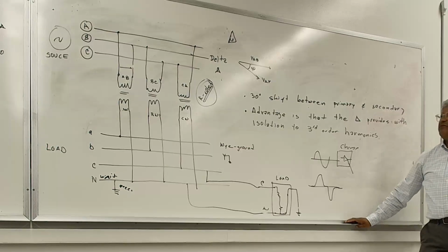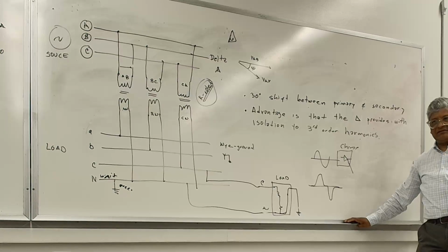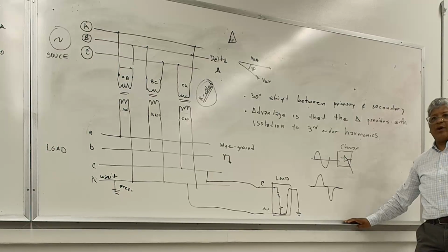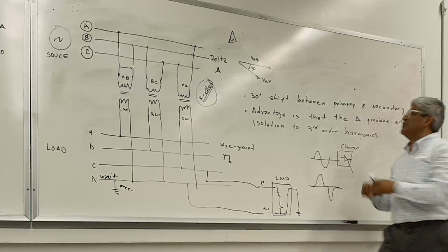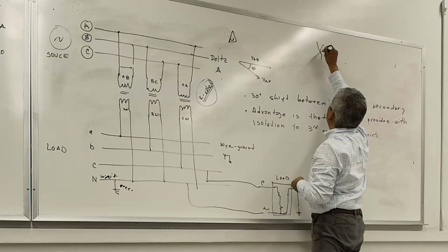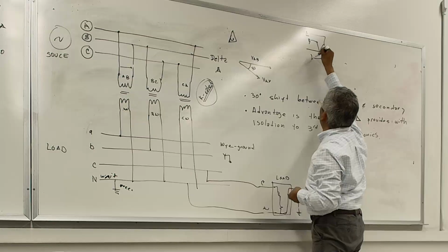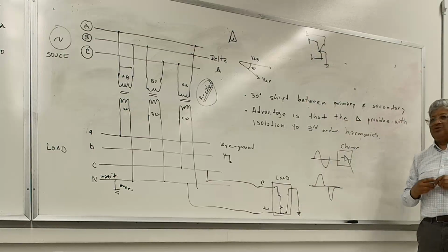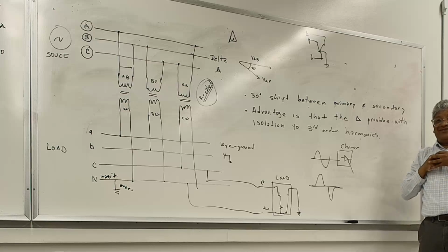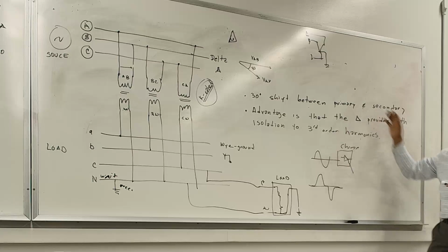Even if I say, oh yeah, the 500 kV system is Y grounded at the substation, you don't build a neutral. You don't take this wire like this on the 500 side. The line only has these A, B, C wires. This right here is grounded, but it's never used. You don't use that because you're not connecting those on the 500. Do I make sense? Yeah. Where you start needing grounds is once you get to the customer. That's when you start needing grounds.